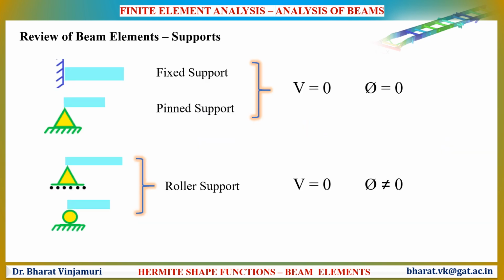The following are the supports in the beam elements. The translation is considered 0 for all the supports shown in this figure, including the fixed support, pinned support as well as roller supports, and the beams are allowed to rotate in case of roller supports.